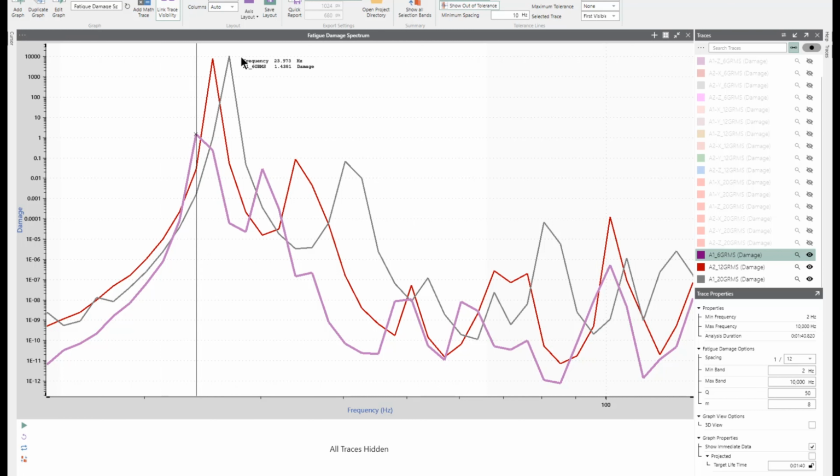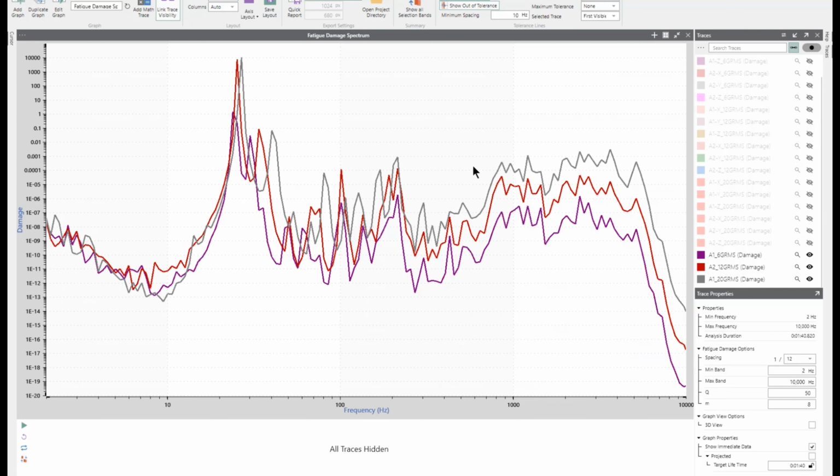And then you can see that each one, as we change the amplitude, so nothing else is changing, the mass is staying the same, the position is staying the same, but as we increase amplitude, that excitation frequency is shifting higher. And that can be a cause of issues in certain tests, especially when you start looking at some of these secondary harmonic bands where that shift is even more visible.